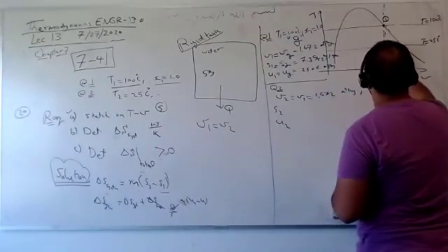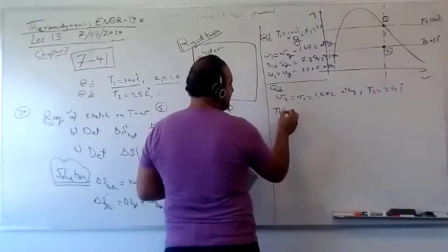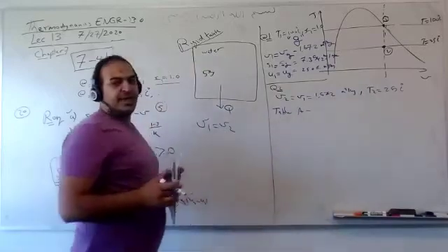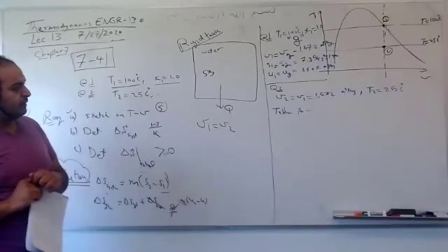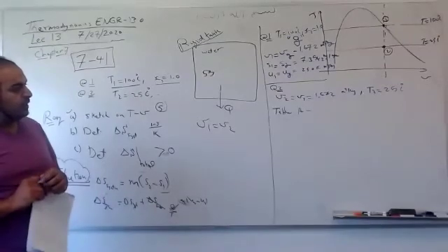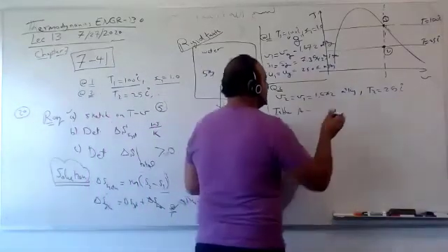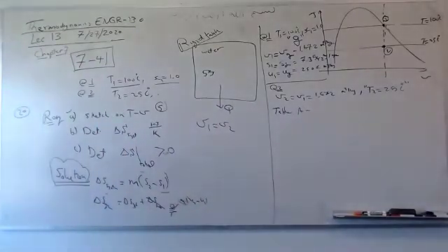Looks like this is a saturated mixture. So which table, guys? Which table? Mixture. Mixture air, mixture water. Table A4. Why? Why not A5? Because the temperature is input. Perfect. Temperature is input. The tables, fortunately, use Celsius. But when you have an equation, like for example the ideal gas law, where you are substituting temperature, you need to have it in Kelvin.